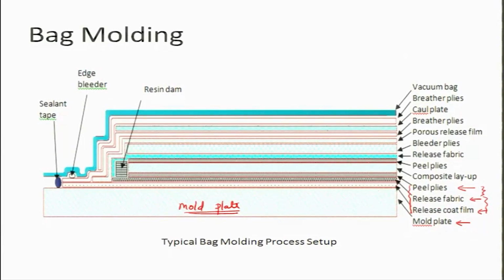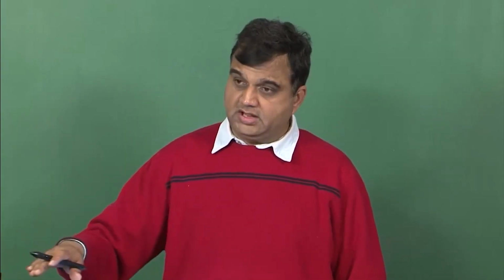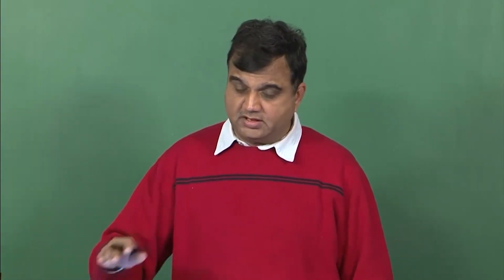So once these three things are done, then you have a composite layup. These are composite layers. If these layers are made up of just fibers, you put them layer by layer, and each time you put a layer you put some matrix material, roll it, make sure all the air is squeezed out, put another layer, and so on.